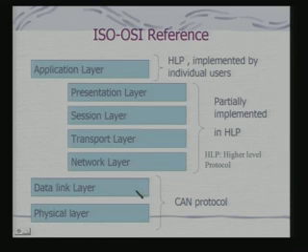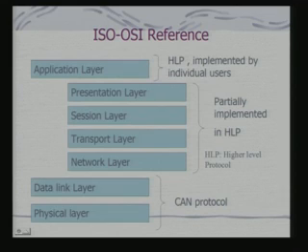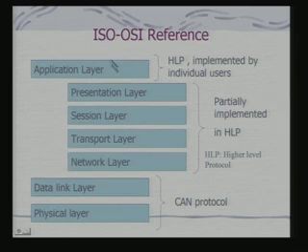Say, for example, if I have these two specifications available with me, what happens? I can use components as well as CAN controllers from a variety of sources because they will all be compatible with these two specifications. Just like today you can buy an Ethernet card for your PC from a number of vendors because all of them are consistent with respect to that standard. Similarly, you can have CAN protocol consistent components for these kinds of applications, and a particular car manufacturer can have higher level protocols implemented on top of these two layers.